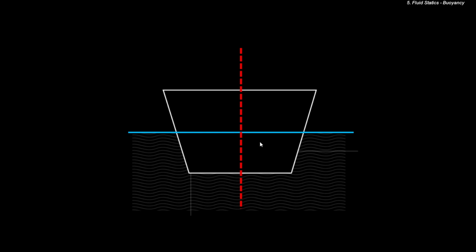So now let us consider this particular object, and this is the center of mass, and the center of buoyancy will be this, and it will be calculated, I again repeat, with this particular volume in mind. If I call this A, B, C, D, that A, B, C, D volume will give us point B, that is the buoyancy.